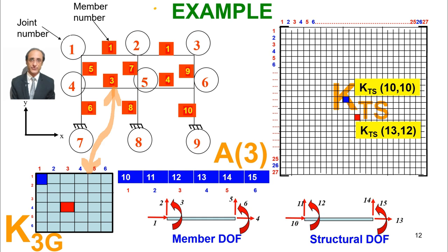We know. So we can do this for all the elements. But then we have to do it for each element. We cannot take advantage of symmetry here. We have to check all these. Symmetry we have to see for this KTS. We say that okay, we will only form the lower triangular half. So if we find that an element is going to the upper triangular half, we don't send it. Like for here, the maximum is 15. So some elements go to the upper triangular part also.